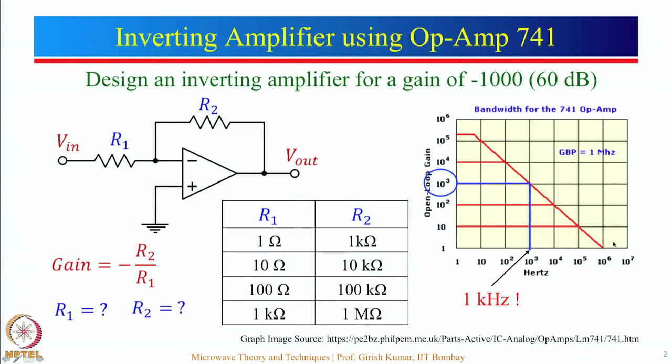Now, from here we will shift to the very high frequency, and that is microwave amplifier, but I just want to bring to your attention one more time, the gain decreases as the frequency increases. Now, this is 1 megahertz. If we go to 1 gigahertz, gain response will be extremely poor for 741 op-amp. In fact, it will not even work. But I want to mention there are several op-amps that have a gain bandwidth product of 1 gigahertz to even a few gigahertz. So, if you want to use an op-amp at very high frequency, it is better to use those op-amps than to use 741 op-amp.